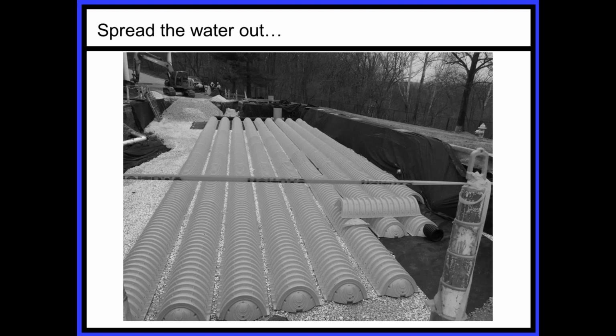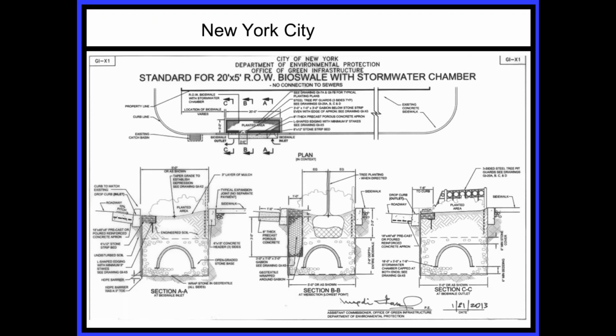Very similar to what I talked about in bioretention versus pervious pavement. Bioretention has a small footprint on the bottom, so the infiltration capability is less than pervious pavement with a broader area for infiltration. New York and other larger cities have had to deal with stormwater in interesting ways. This is actually from New York DEP's manual of stormwater management, and what you see here is a replacement curb with infiltration surfaces like porous concrete or pervious pavements, and what that allows is water to infiltrate down into a chamber that then holds the water.